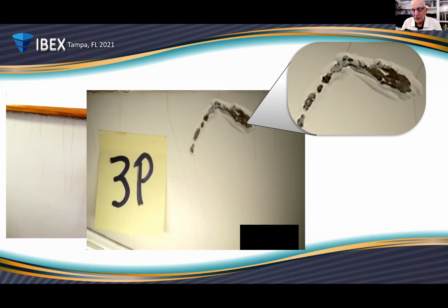There's not a great way to spray that. So in order to get the right amount of gel coat on the sides of this deep well, you're spraying at an angle up here. What happens is it tends to load up the bottom.